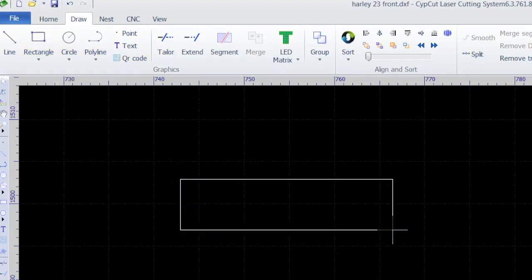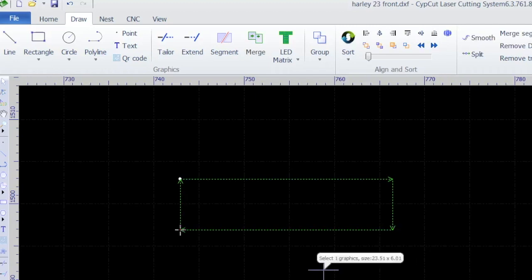And if you drag and release, what I found the best to do is just go ahead and get your basic shape drawn. And really, I mainly just use the drawing to process offcuts. So if you end up with sheets that have large areas that you want to cut and save as an offcut, you can draw that.